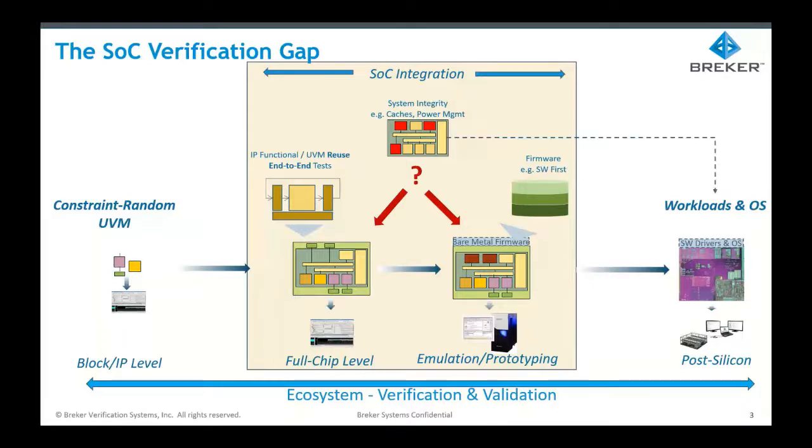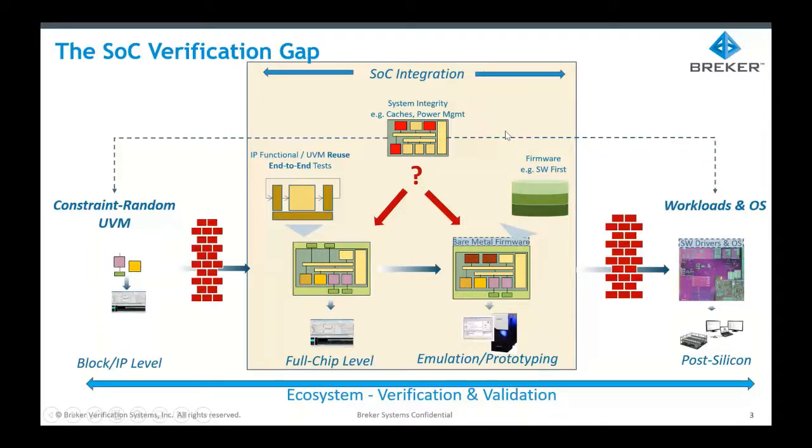The second issue that we have is that those are some good tests that we're going to write. However, we cannot reuse them. We cannot reuse them in post-silicon, and it's actually hard to go backwards. We can take UVM components and UVM tests and port them forwards to the full chip, but there is no backward compatibility that we can do. So all these tests end up just being in a silo. You can think of it as we have created some kind of wall between our SoC integration and all the other activities, the UVM and the post-silicon.